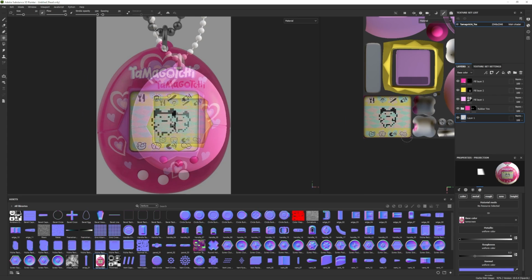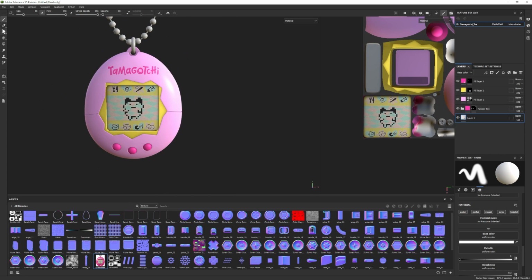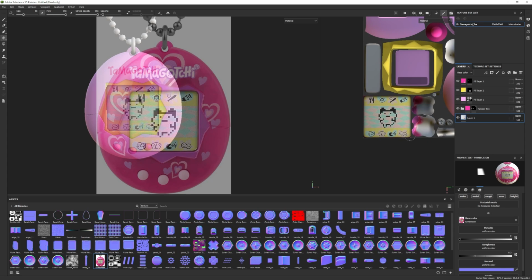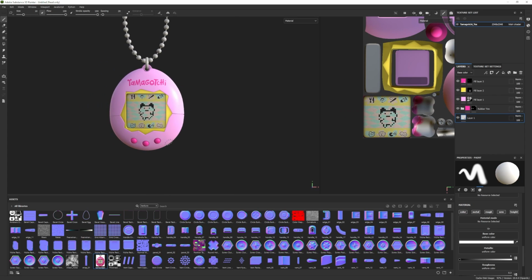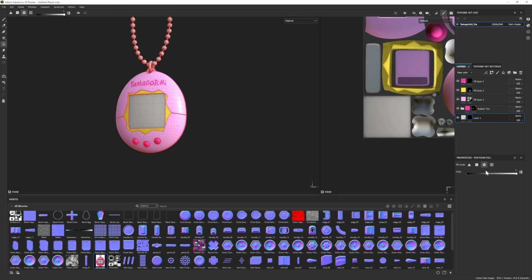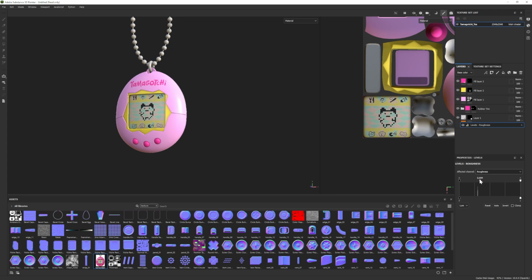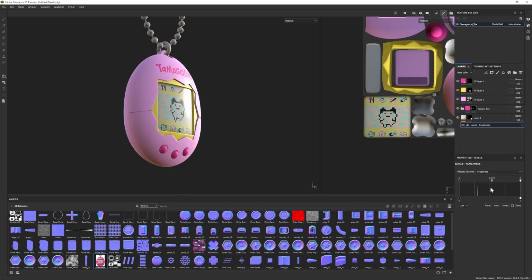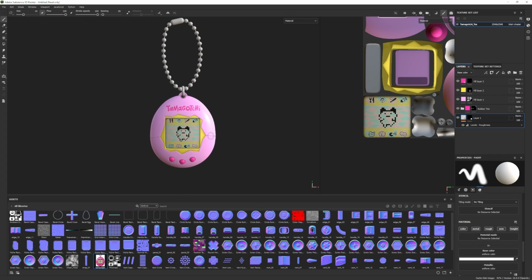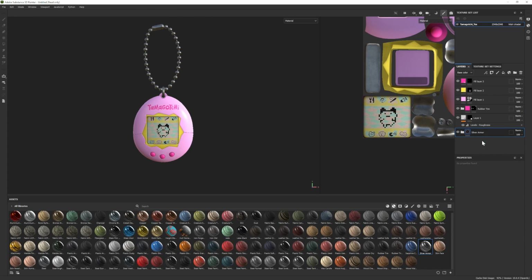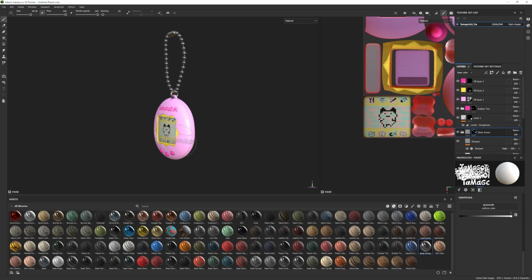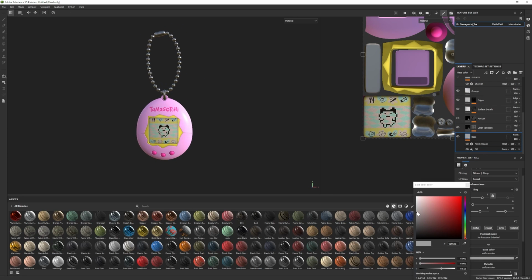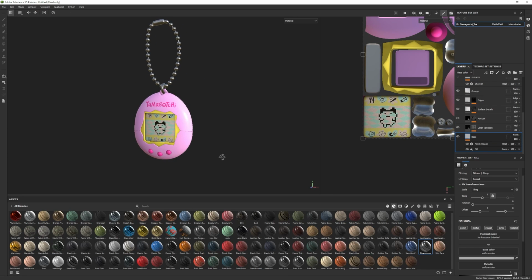Now, like always, I'm sure I'm like a broken record. You guys will hear this in all of my videos, but I always find it's important to just not worry about dialing in the perfect texture right off the bat. I find that can really drag out the whole texturing process, and once you start adding in different materials around the other materials you added in, suddenly everything needs to be changed, and it can just drag everything out. So what I like to do is just start filling in all those empty meshes with some sort of material. I always like the smart materials. They are really great foundations that you can start working off of. In this particular case, I just use fill layers, just plain textures, just to fill in all those empty meshes.